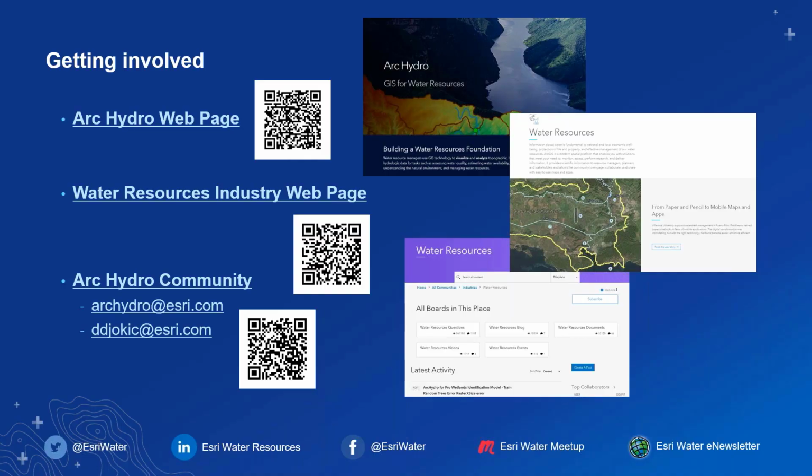Is it in relation to the ArcHydro toolbox or the ICPR4 toolbox in ArcGIS? If it's ArcHydro, Dan can answer that. It just says the Arc toolbox. I would assume, Warren, that it would be the ICPR toolbox in ArcHydro. In ICPR4, if you go to File, Check for Updates, it'll direct you to the download and the install exe for all the Python scripts that go along with that toolbox.